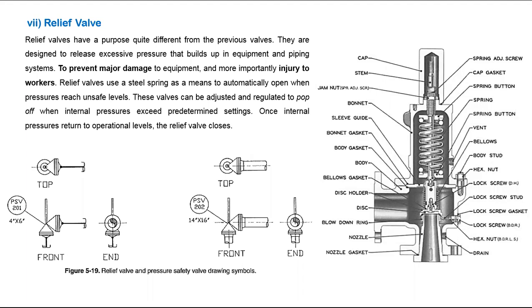Also, you have to use a water hammering arrestor and a backflow arrestor. Everything you have to provide. For the purpose of cost saving, and to save a fixture or pipe from bursting, you have to use a relief valve.